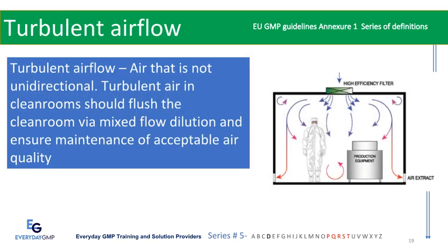Turbulent airflow: air that is not unidirectional. Turbulent air in clean rooms should flush the clean room via mixed flow dilution and ensure maintenance of acceptable air quality.